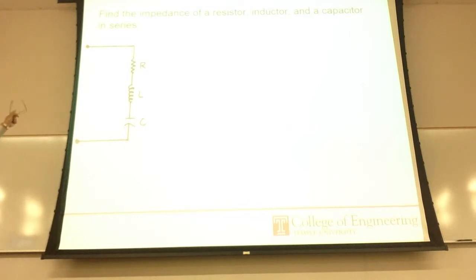If you are given an electrical circuit like this, which is very common, in fact, about 40 years ago you could physically see this. If you opened up a transistor radio or a vacuum tube TV, you would have seen the actual resistors, inductors, and capacitors. Now all of these are in an IC, an integrated circuit. They are so tiny you have to put them under a microscope, but they would still behave the same way, because it is an electrical circuit. So what I need to do is find an impedance for this, which would be equivalent to what we have over here.